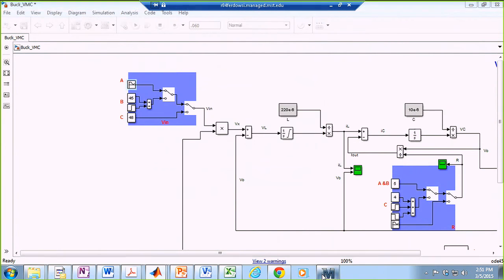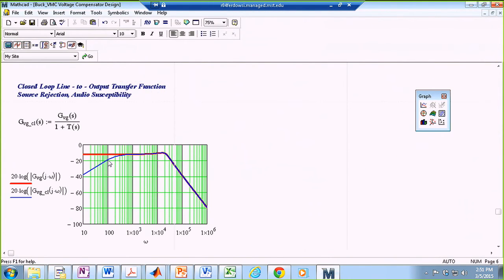Now, if you look at the transfer function at 100 hertz, there is not a lot of extra attenuation. The blue curve, which is the transfer function after the loop is closed, is almost the same as the red one, which is as if we don't even have an integration block. So you can see there is not a lot of attenuation happening here. So this is not good.